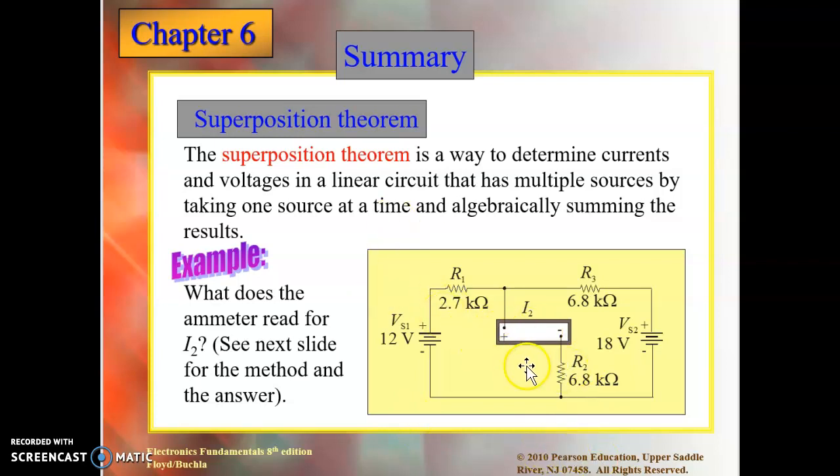So we are going to solve it using superposition because that's what we are learning. But basically, superposition says that when we have different voltage sources and current sources, or a mix, we can have voltage sources or we can have current sources. And the way it works is we analyze the circuit source by source. We leave one source in the circuit and we remove the rest of the circuit sources. We replace each by its internal resistance equivalent. Like if it is a voltage source, we short. If it is a current source, we open. But when we analyze the circuit, it has to be one source at a time.